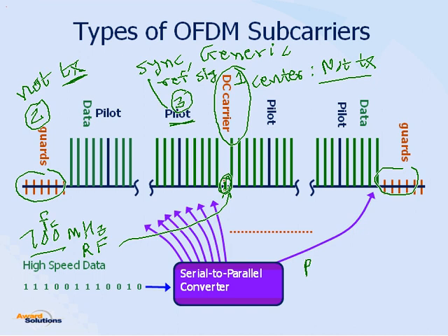So for example, let's say our pilot is 0000, and at that time our data is, let's say, 0110. Now, sometimes the environment will mess up the pilot, so this 0 will become 1. That is our error. At the same time, our data bit will also be in error, because pilot and data will be affected in the same way.